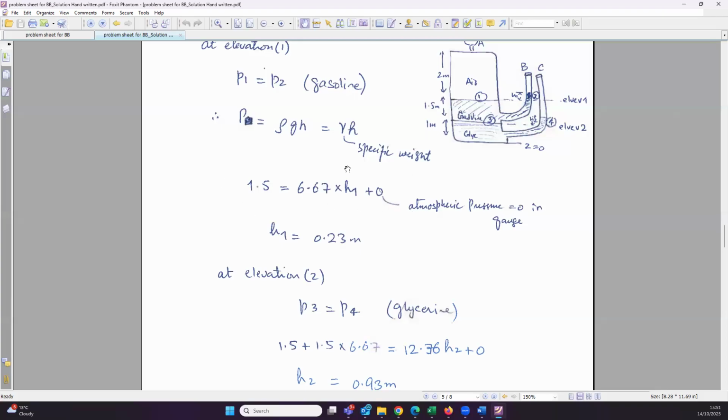It means that we are taking the whole equation without atmospheric pressure, because if I want to use absolute pressure, then I have to change this equation from gauge value into absolute value. So I have to add the equivalent of 1 atmosphere. I cannot add 1 because 1 is not the unit here.